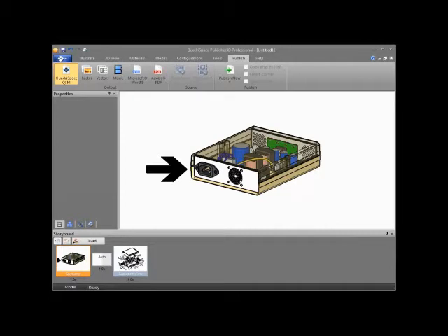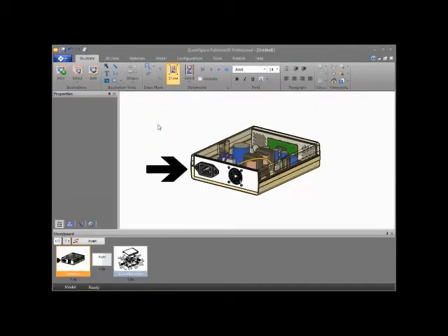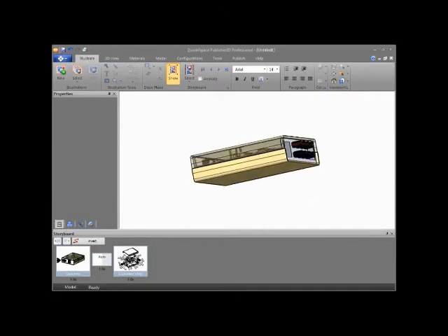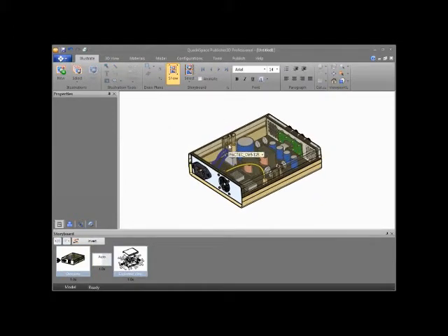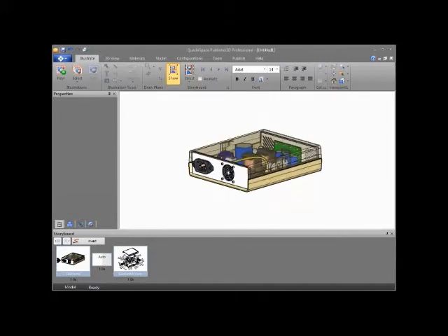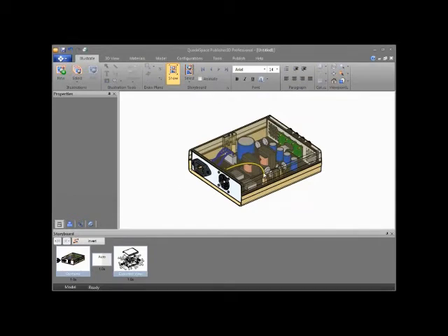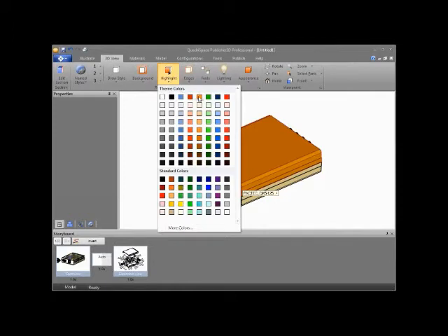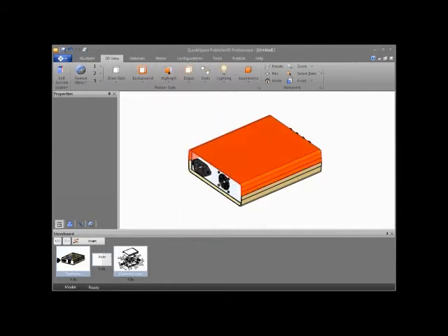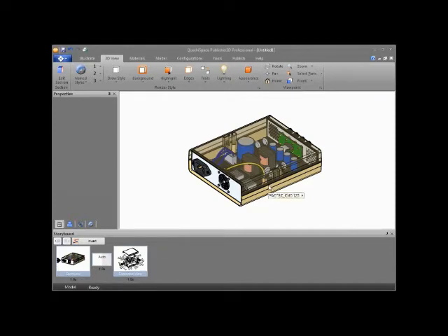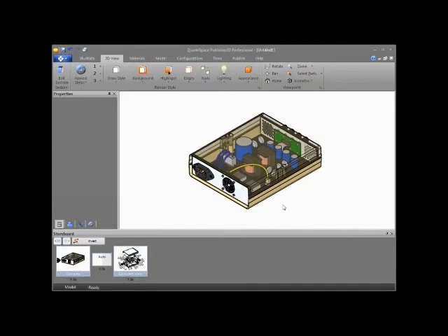We have an exploded view. The first thing we want to do when we do this automation process is set up our view, because that view is going to be repeated. It's going to act as a template, if you will, for the Smart Template Publishing. So let's make sure that our selection color is good. Let's actually pick a little different, brighter color maybe for selection. I think everything else is pretty good. In the orientation, let's get one of the exact ones. Let's take a straight up isometric there.